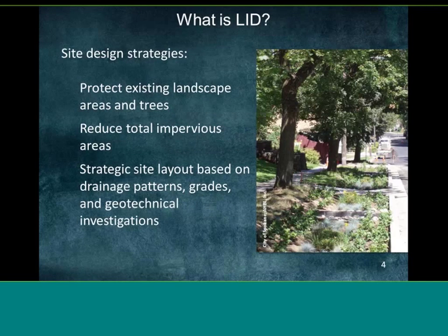And LID is also a strategy for development where you're protecting existing landscape areas and trees for the services that they provide. You're reducing total impervious area in a site design, and you're also strategically laying out your site to respond to the existing drainage patterns and the grades, and also any geotechnical investigations that are being done.